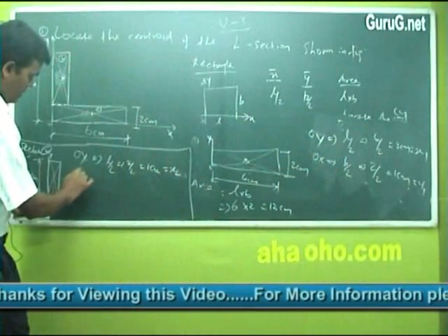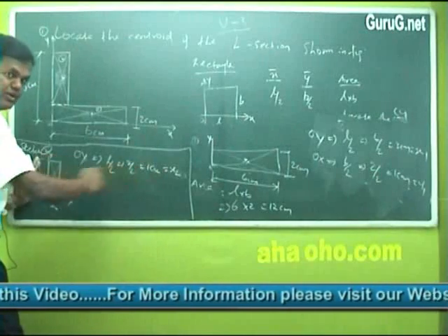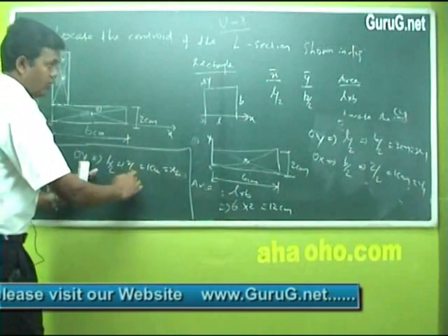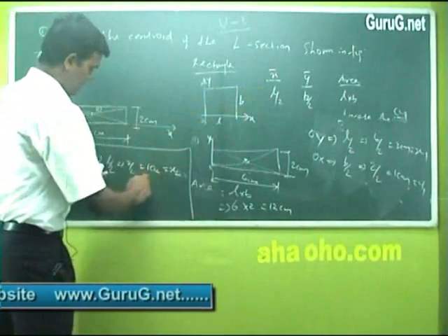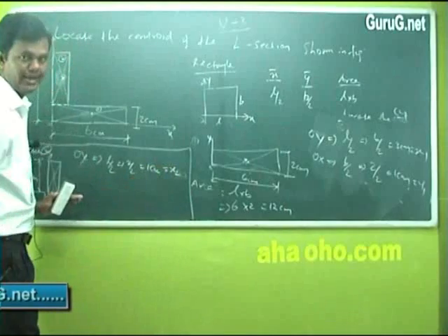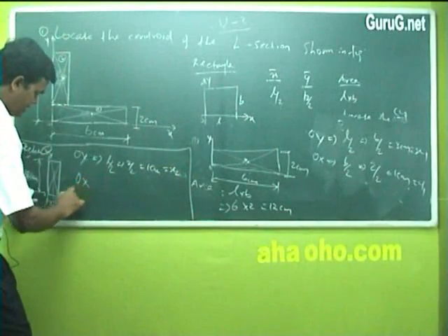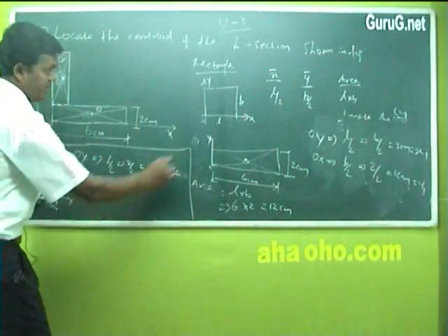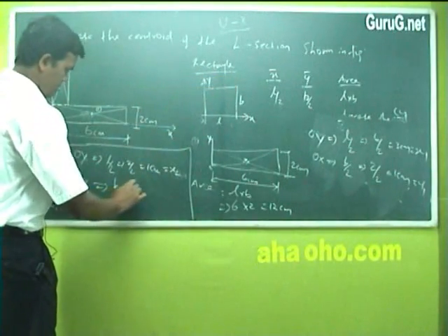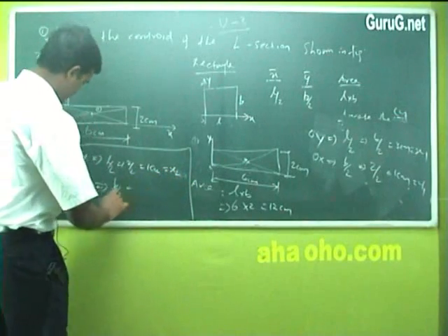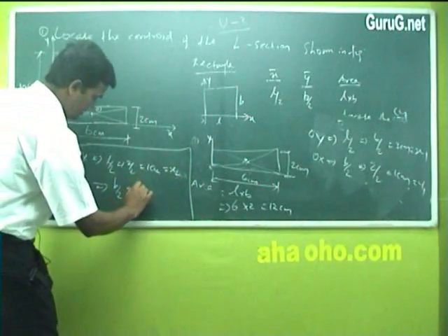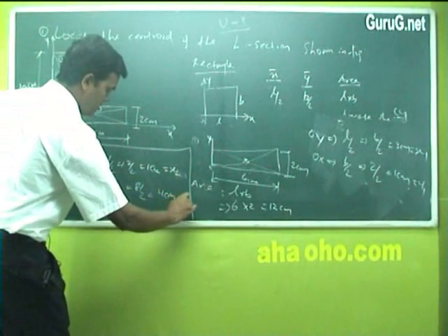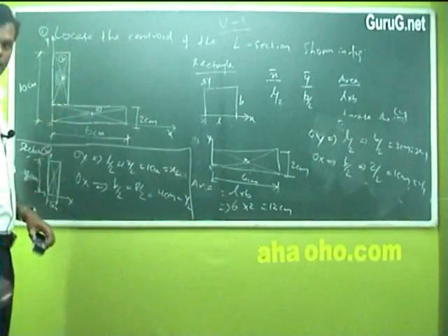Right? Now here, from OY I travel towards the x direction. From OY it is L by 2, it's 2 by 2. The formula is always L by 2. And I get 1 centimeter for my x2 value. Now from OX I travel up, right? I will have B by 2 as my formula. Y bar will become, what is B here? 8 centimeter here. It is 8 by 2, becomes 4 centimeter. That's my y2 value. Is it clear?